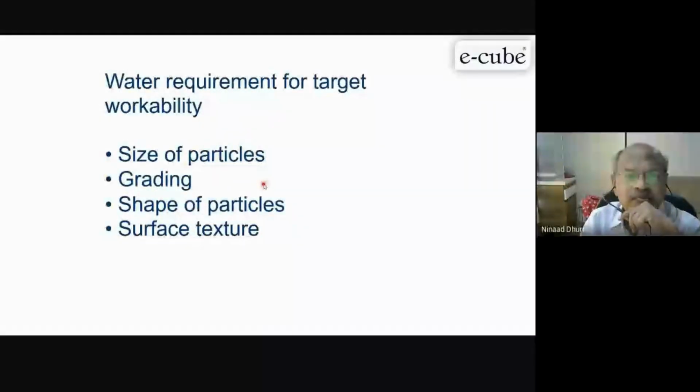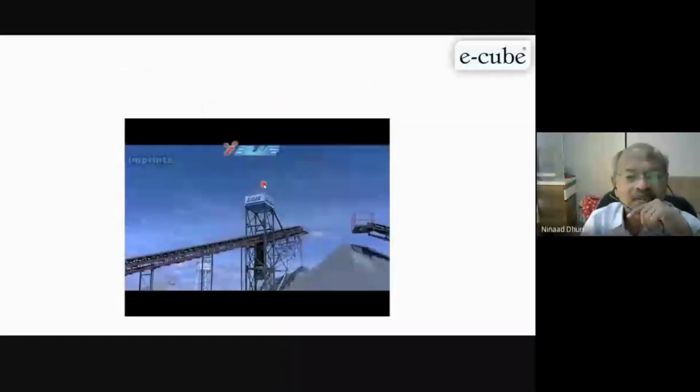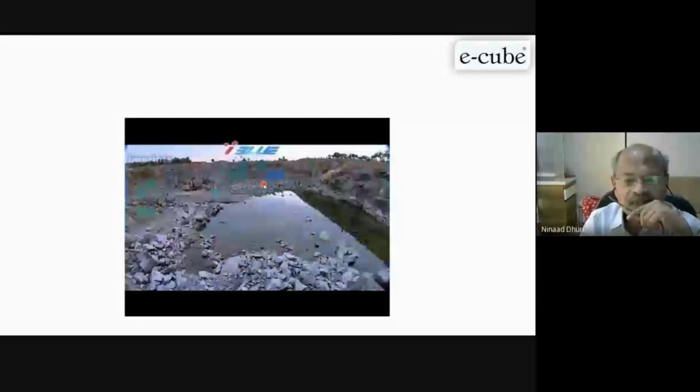So workability target requirement, size of particles, grading, shape of the particles, and surface texture are very important. These are also things you have to understand and proceed with for your mix design. This is one video that is there.